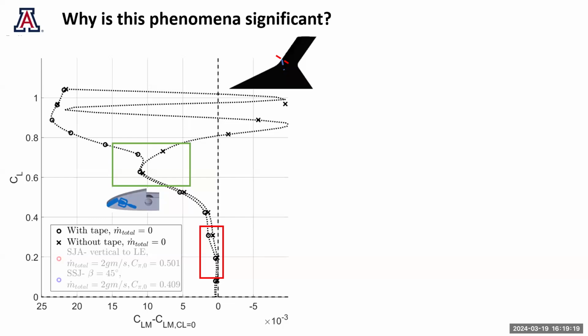But at smaller alpha, you do not see any difference with or without that slot. So for this liftoff process that we were looking at earlier, if we introduce a slot around that location, we can get either pitch down, signified by negative pitch values, or nose up, signified by positive pitch values.